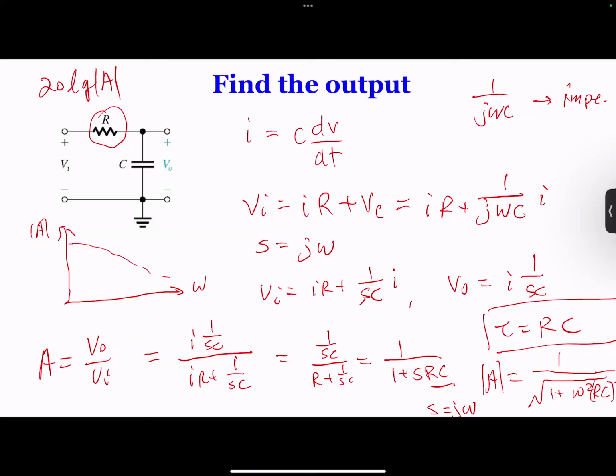Because in this case, if your gain is 1, what will be the dB? 0, right? So 0 corresponds to a gain of 1, which means 0 dB increase, 0 dB decrease. Input comes in, input comes out, same, no gain. So that's 0 dB. It's very easy to understand now why they use this, because 0 means no gain, in and out.